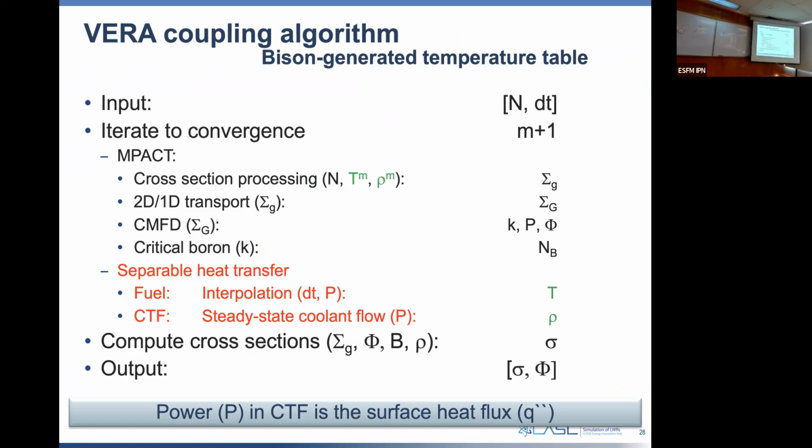So there are actually a variety of these fuel temperature things that can all kind of work independently. So one approach was before we had a solver for temperature inside of Cobra because it was a flow code. It didn't have a fuel model. We said we needed to add a fuel model. And so we just created a little interpolation function. And we said, let's run Bison a whole bunch. And just like we have cross sections interpolated for lattice physics to core diffusion, we said, if I tell you the power and the burn up, and here's my time, you tell me what my temperature should be. And so we created some simple Bison generated model.